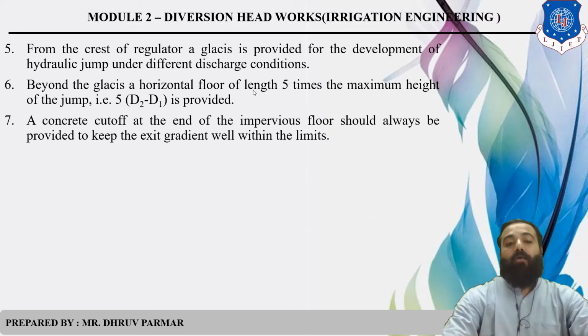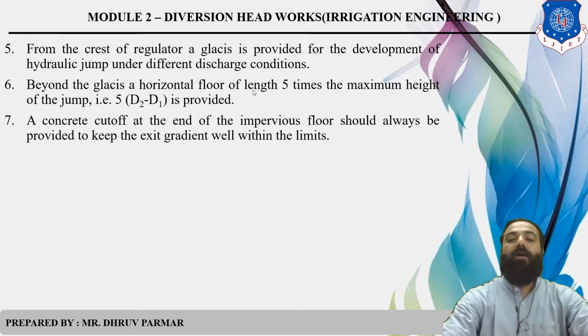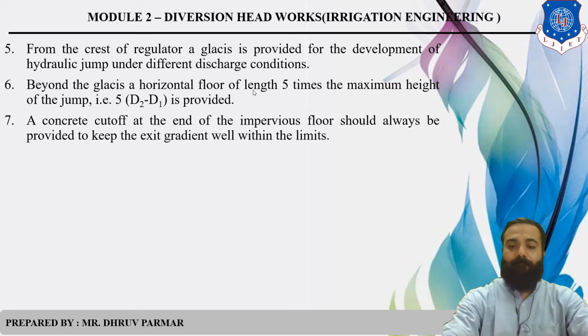Then a concrete cutoff at the end of the impervious floor should always be provided to keep the exit gradient well within limits. Meaning a cutoff or pile is provided at the downstream side as well as the upstream side to keep the exit gradient within limit. Exit gradient means the slope at the exit point, otherwise at the downstream point of the weir, or we can say the dam, called exit gradient.